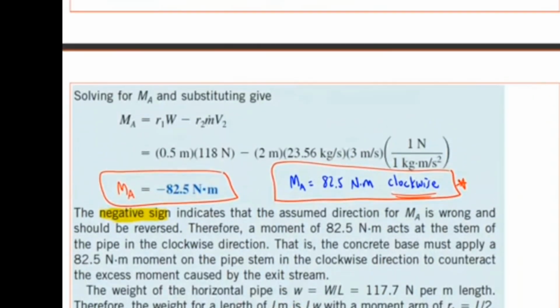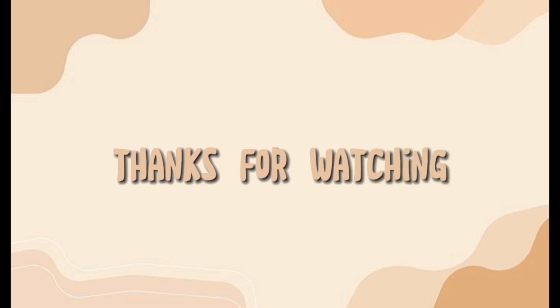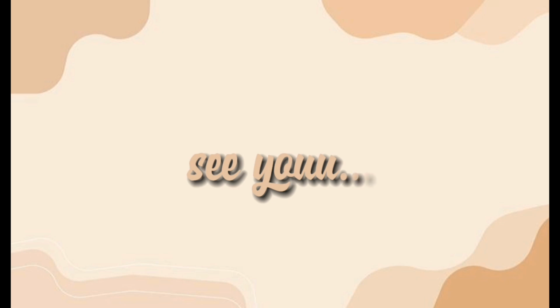We want to find that weight such that there's no net moment. MA would be 0 at the base of this pipe. We want to solve for length L of the horizontal pipe that causes that moment to vanish. We use the same equation here but set MA equal to 0 and solve for length L.